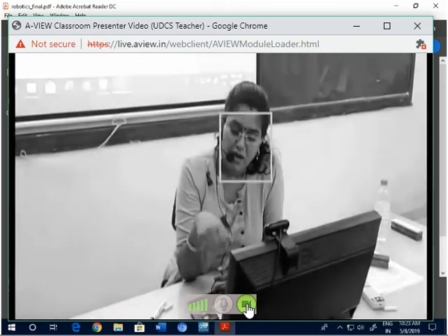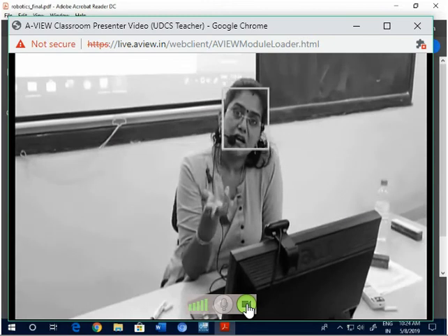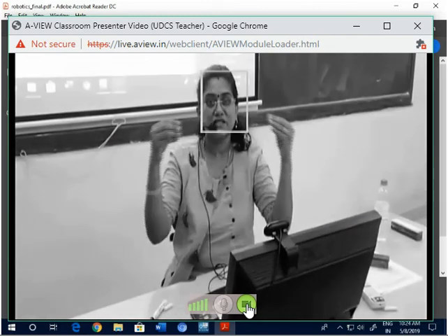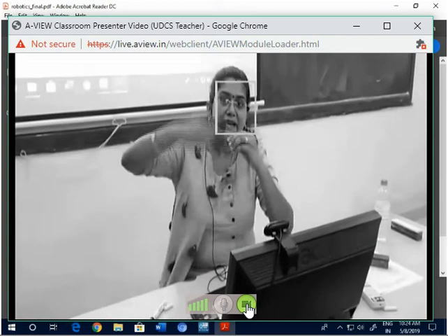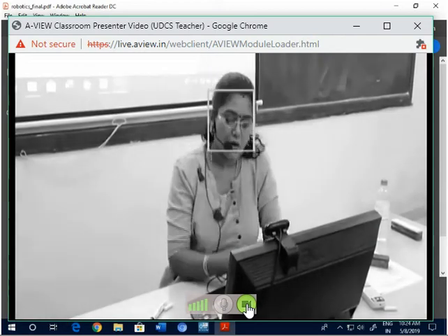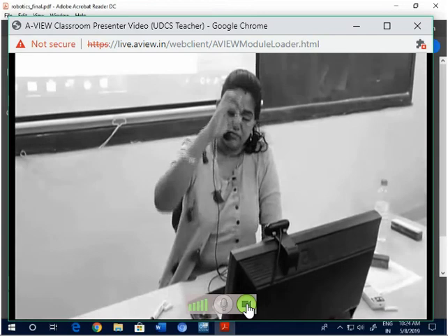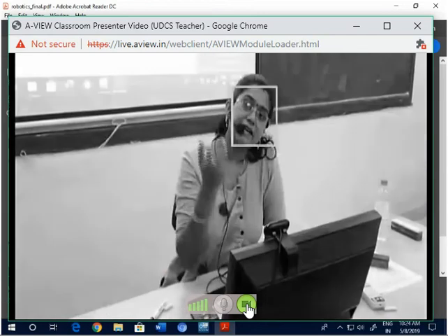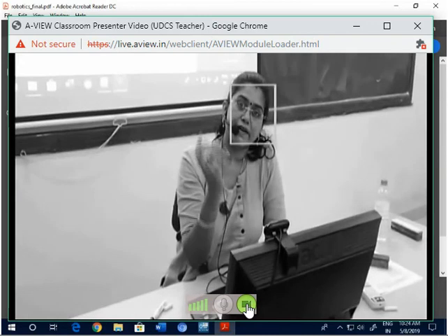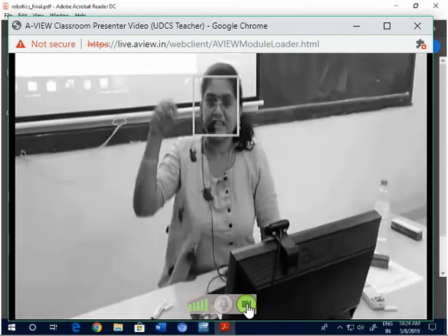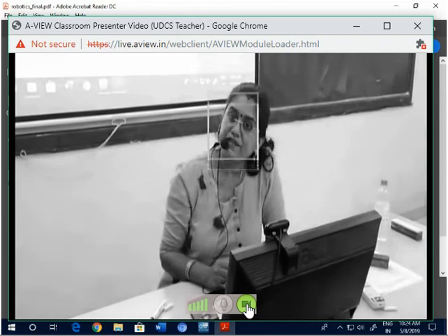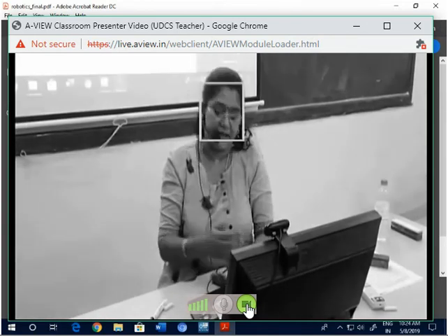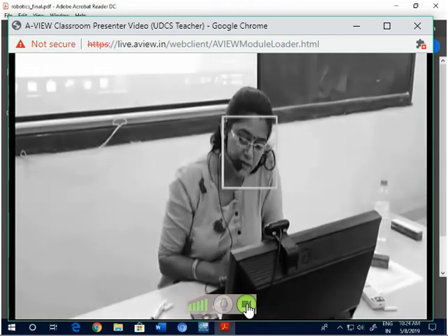Now see, in a robot we have 2 types of joints: one joint which moves linearly in and out, and one joint which rotates 360 degrees. So your joint may be prismatic or revolute. Fine. So how will you represent them? If it is a rotary joint, qk will be equal to theta k. And if it is prismatic, a linear one, then your qk will be equal to dk. Right?